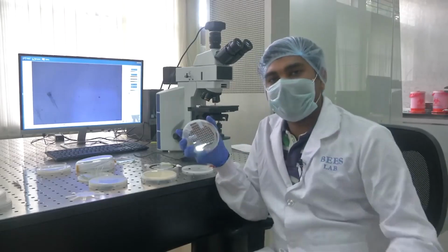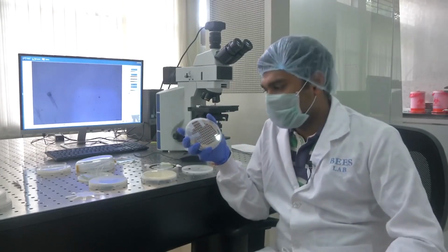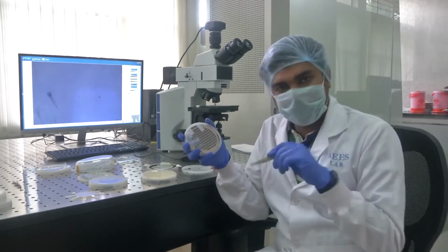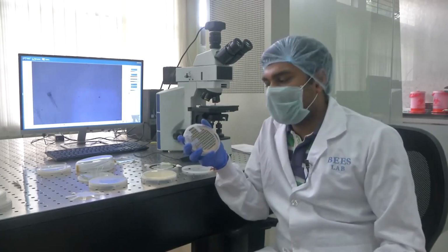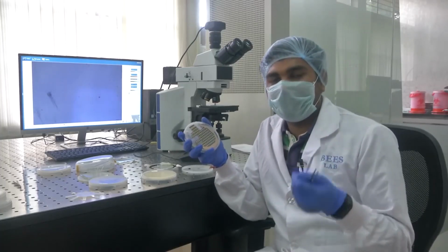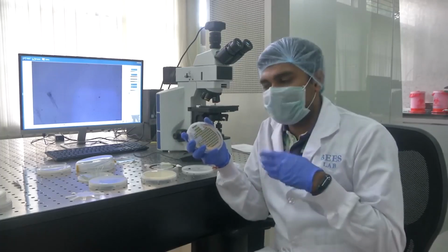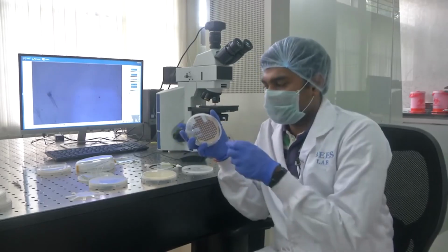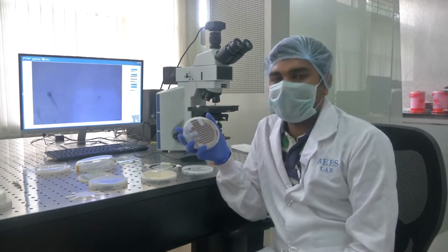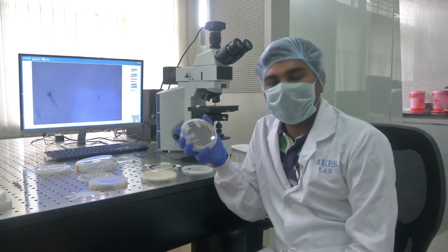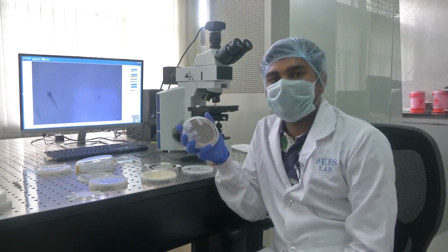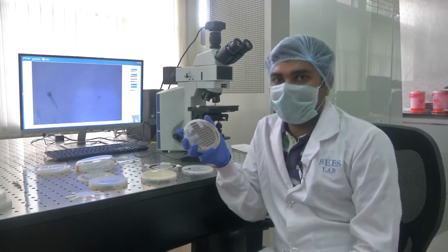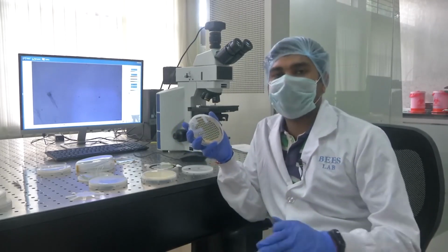Dicing is done using an automatic dicing machine that is available in the institute, and we give the pitch and spacing of the devices, and that machine will go around making X and Y lines on your wafer. It's a very sharp tip dicer, and it will make these lines on the wafer, and the devices will come out. You can see these dicing lines on the wafer. Now this is a special design that incorporates micro heaters, resistance temperature devices, electrodes, isolation trenches, a lot of things on this device. I will not go into the application of it because it's still under research, but I can show you the design as such.